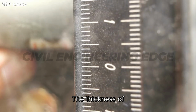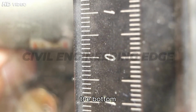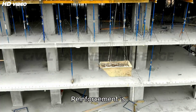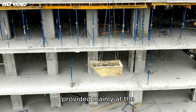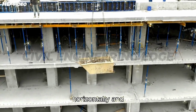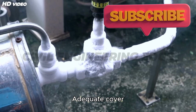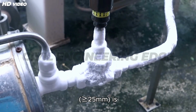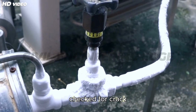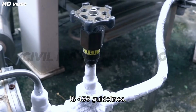The thickness of the stem varies, thicker at the bottom, approximately 300 millimeters, and tapers to the top, approximately 150 millimeters. Reinforcement is provided mainly at the rear face tension zone and placed horizontally and vertically as per calculated bending and shear forces. Adequate cover, 25 millimeters, is provided, and the stem is also checked for crack width, deflection, and durability per IS 456 guidelines.